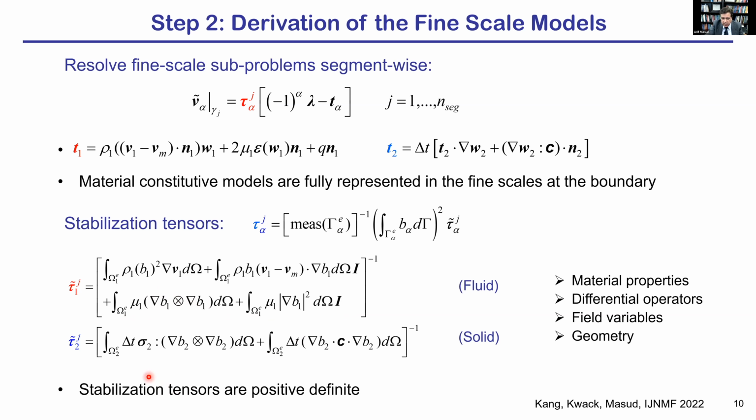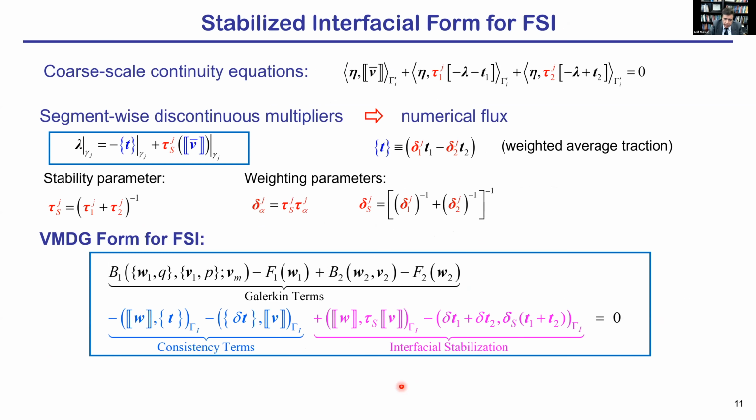While for the solid, it is the operators of nonlinear elasticity that are acting on this field. So these are unambiguous, we can completely derive them. And tau is a composite function, so it means that the error at the interface, we can account for all the features there, both the equations, the material properties, and also the change in geometry, as I will show for finite deformations.